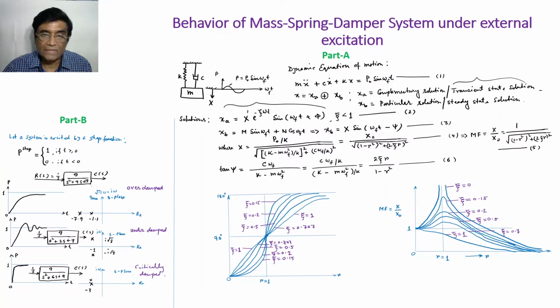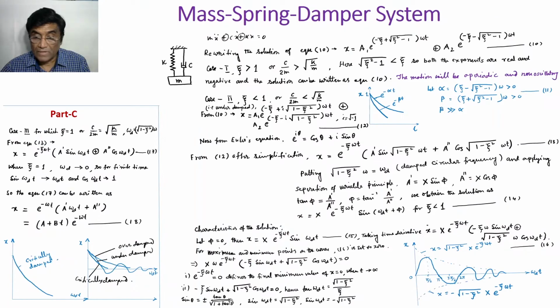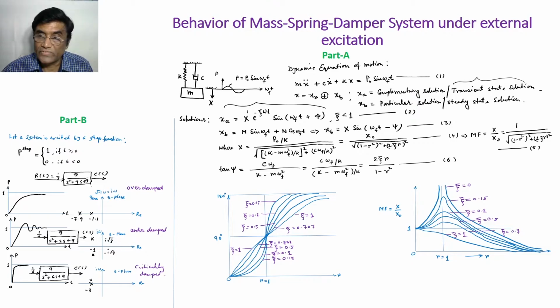So this one is the amplitude, damped oscillation, and this is how the oscillation will take place. This is already corresponding to the transient state response. We will be following this. Now another solution will be like this: m is a constant, n is another constant. There have to be two constants because it is a second order system, and we are assuming that the solution will be something like m sine omega f t plus n cosine omega f t.